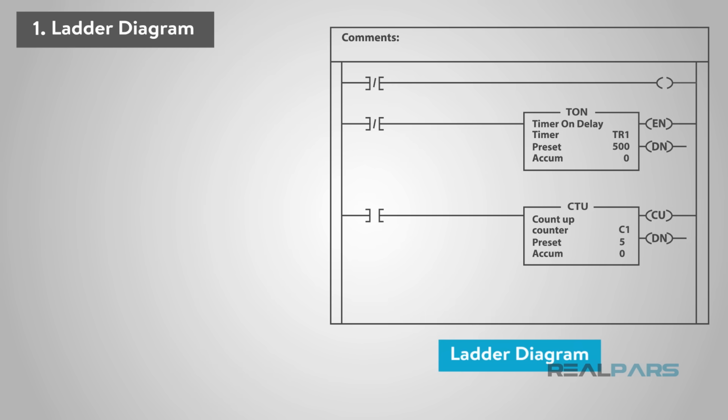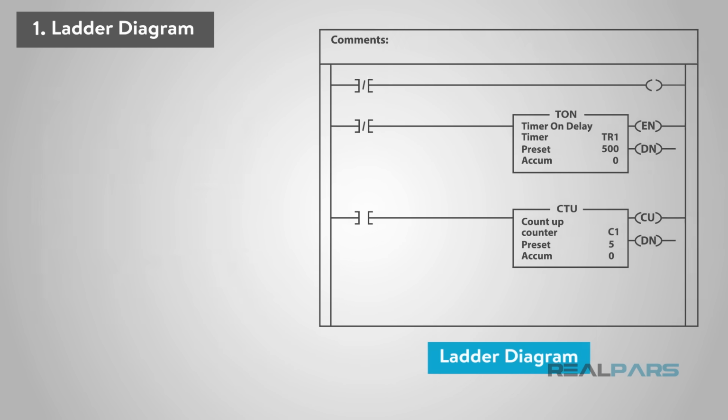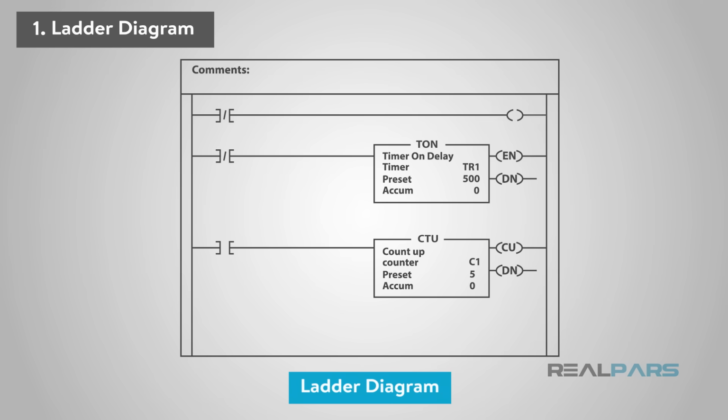Ladder Diagram was originally modeled from relay logic, which used physical devices, such as switches and mechanical relays, to control processes. Ladder Diagram utilizes internal logic to replace all except the physical devices that need an electrical signal to activate them. Ladder Diagram is built in the form of horizontal rungs with 2 vertical rails that represent the electrical connection on relay logic schematics. You can program all the necessary input conditions to affect the output conditions, whether logical or physical.